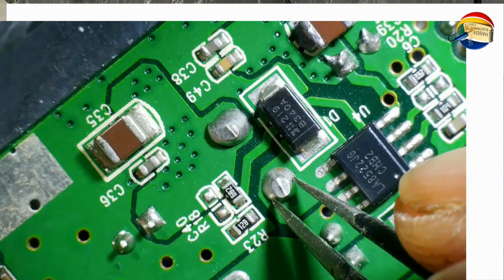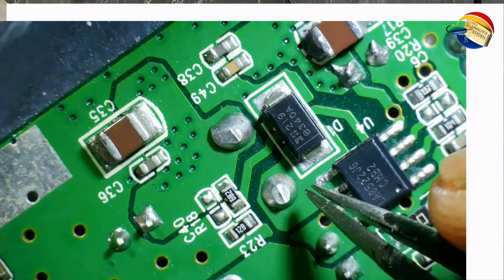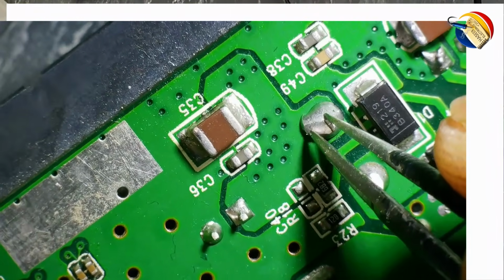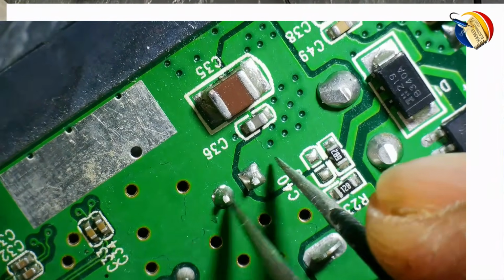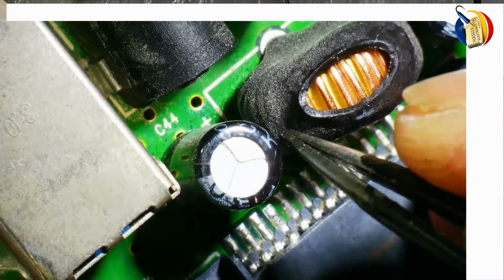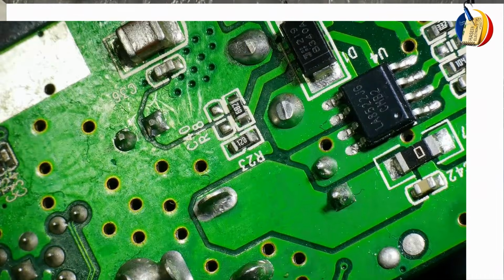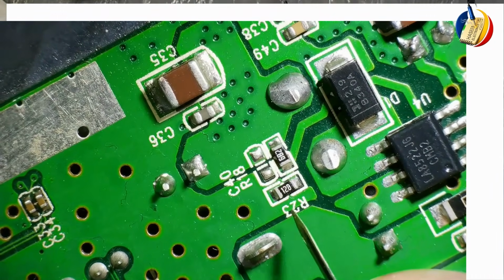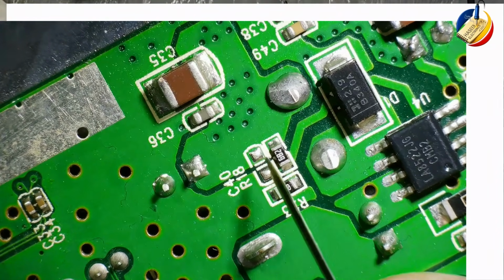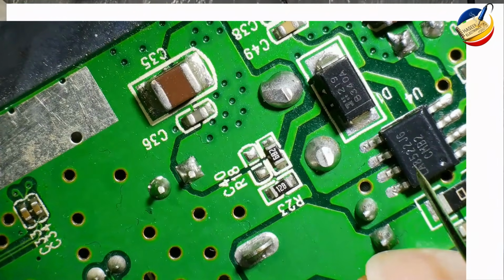The magnetic field in this inductor will build up and collapse at 300 kilohertz. The same way, here is the freewheeling diode. The voltage will be stored at this capacitor, that is this one. This one. Here are two resistors, 6.8K and 12 ohms. Feedback resistor. This end is ground, this end is the output terminal, and this point is reaching pin number 1 of this IC.